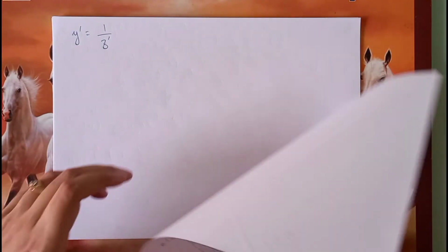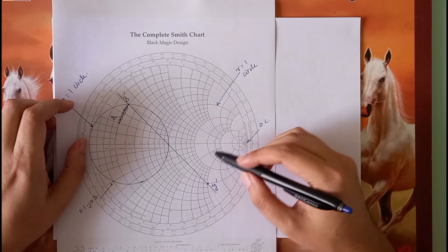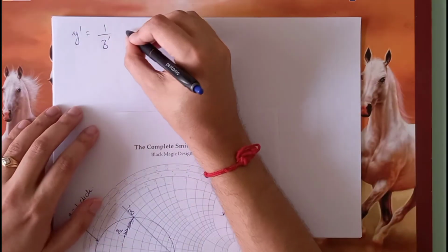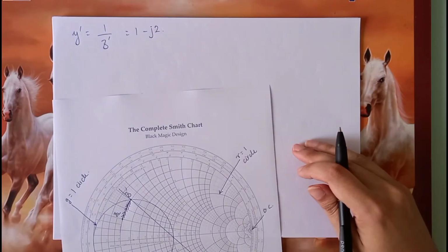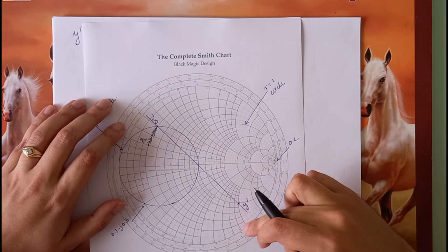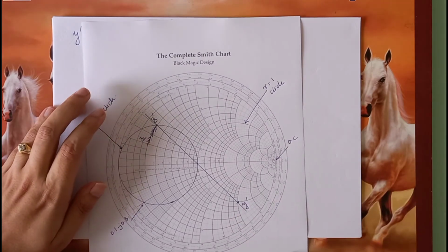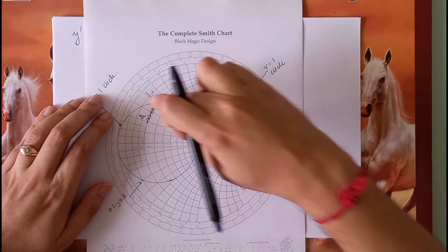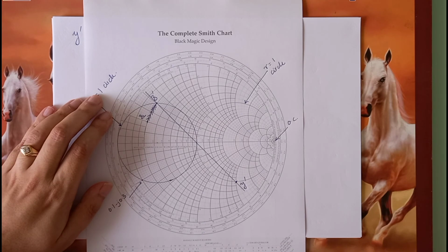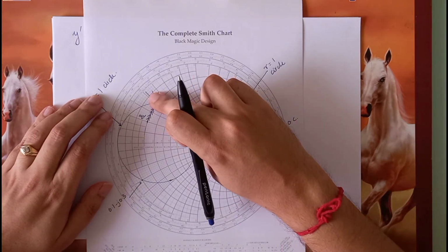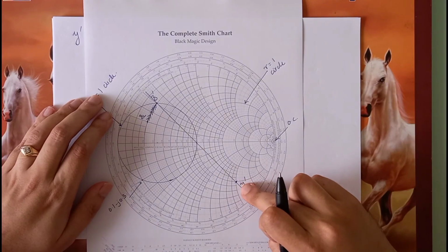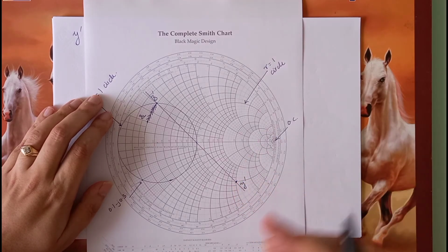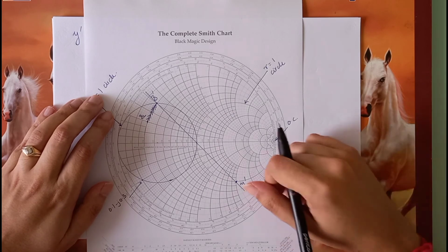We can very easily mark that point out from the Smith chart, and that is 1 minus J2. 1 because of this circle and J2 over here. Minus because it is in the lower half. Now finally, we are over here. Now notice that we have just changed the coordinates. We have not added in anything. The Z prime impedance point has an admittance of Y prime. So we have just changed our frame of reference. But by doing so, we have transformed from impedance coordinates into admittance coordinates.